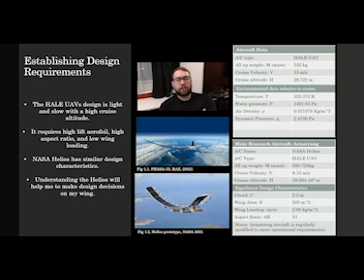By observing the aircraft data table, you can see what is required for my high altitude, long endurance UAV. Researching how UAVs with similar parameters to mine work, they are lightweight, low speed aircraft that fly at incredibly high altitudes. They require high lift airfoils, utilising high aspect ratios and low wing loadings.